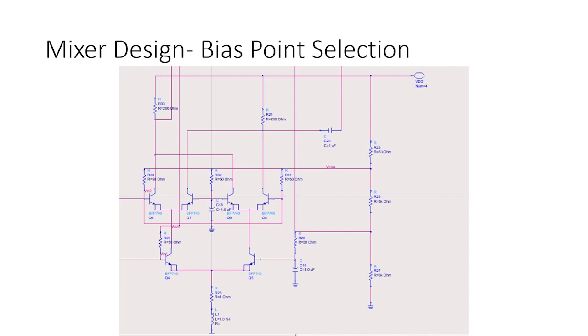According to the data sheet, we find that for the transistor to function properly, the VBE has to be biased at 0.8 volts. We choose the resistors accordingly to bias the transistor. The capacitor used in the bias node will prevent high frequency noise and feed-through signals from affecting the operating point.